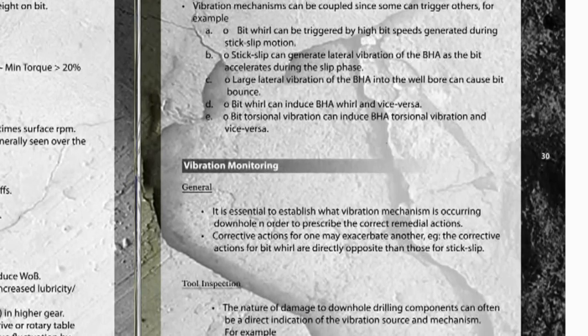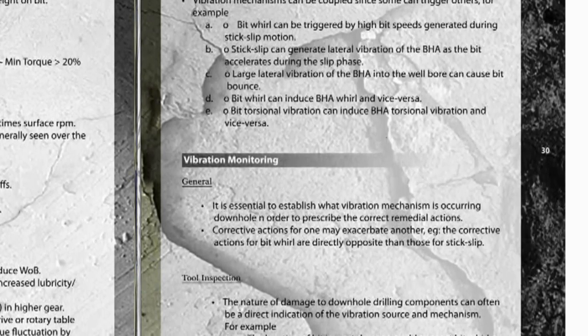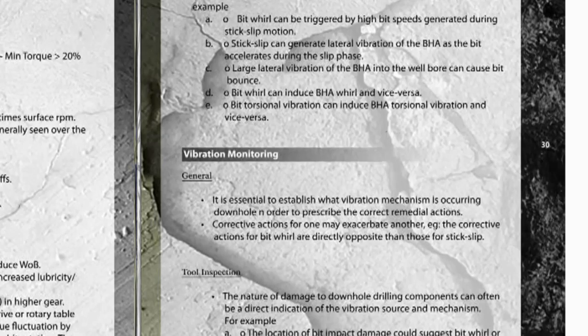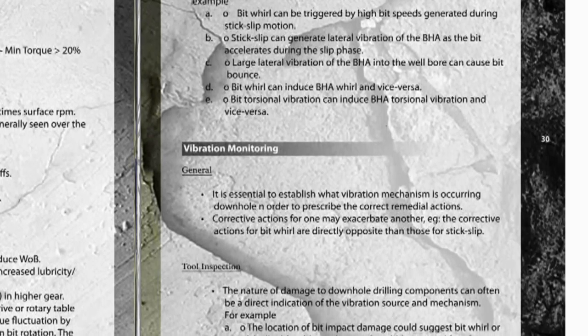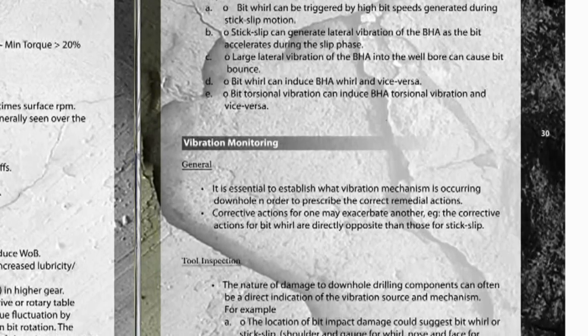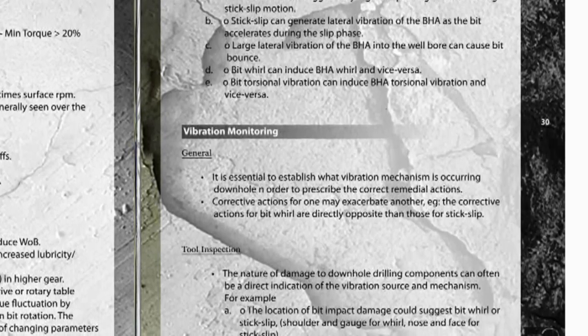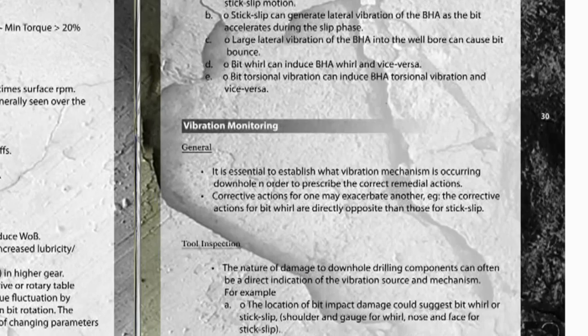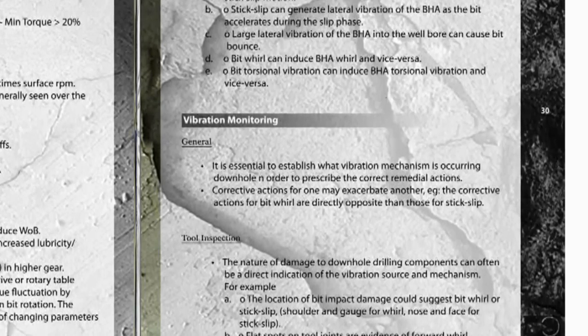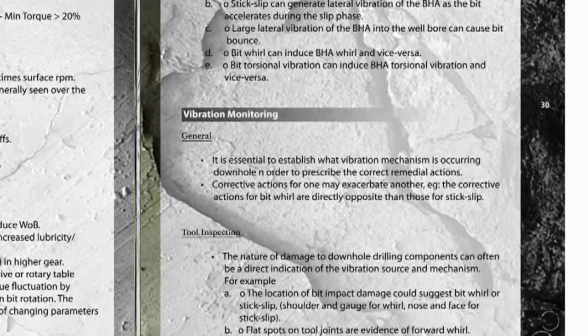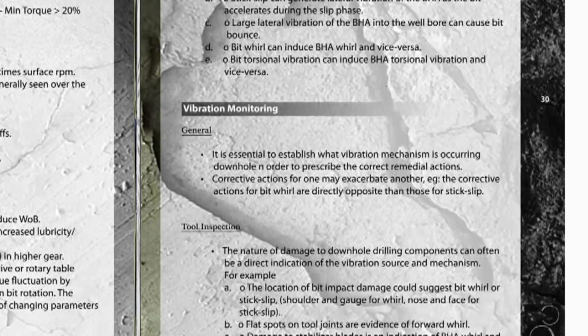Vibration monitoring. General. It is essential to establish what vibration mechanism is occurring downhole in order to prescribe the correct remedial actions. Corrective actions for one may exacerbate another. For example, the corrective actions for bit whirl are directly opposite than those for stick slip.